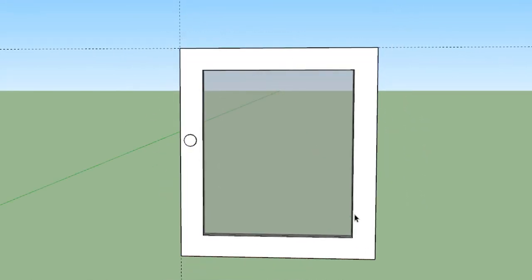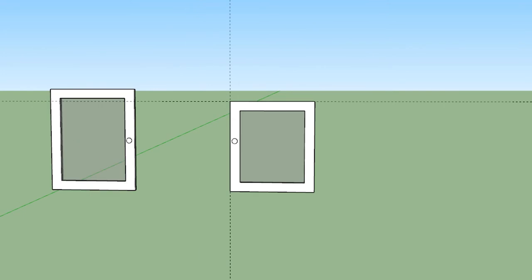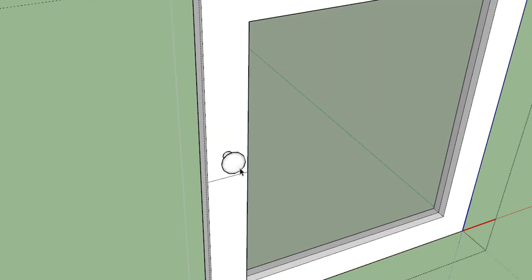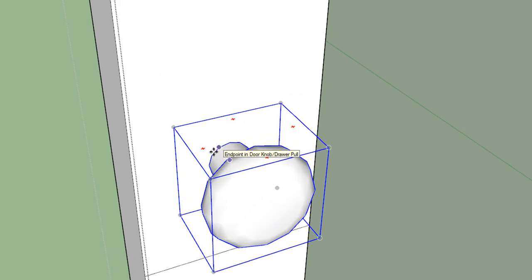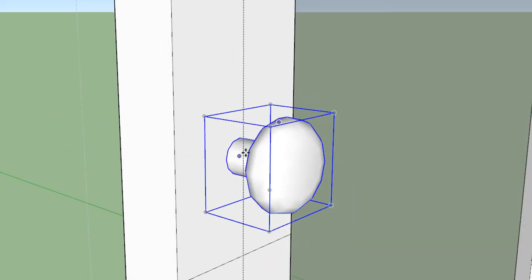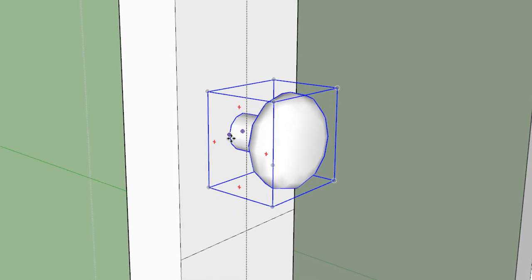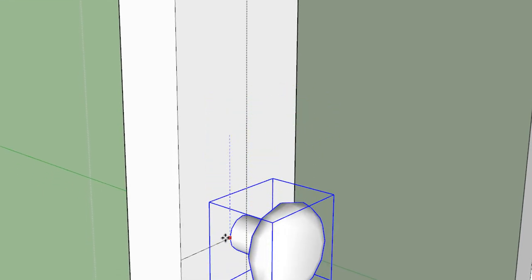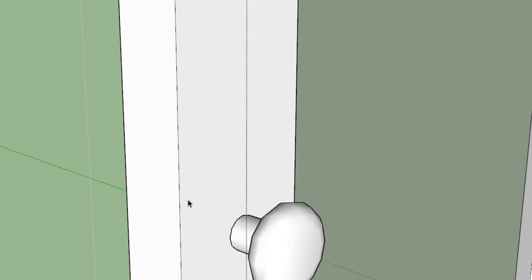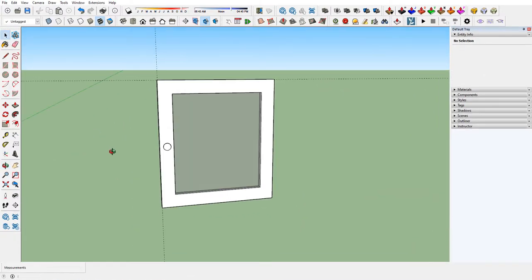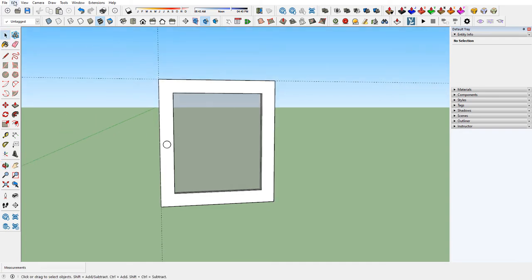So that door is set okay, but the knob is not quite right. We'll draw ourselves a line from the midpoint here to the midpoint there, and then I'm going to do the move tool, select the knob, move tool, I'm just going to grab the midpoint here of the side. There's little bumps on the side here, because this is all segmented pieces. This is good. Click. I'll go down in the blue until it snaps right there. See, it'll grab right there. Click. This is now the right size. Edit, delete guides.